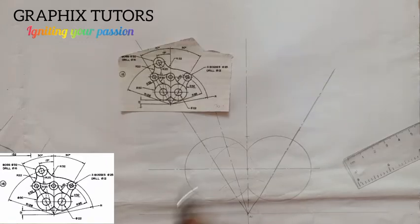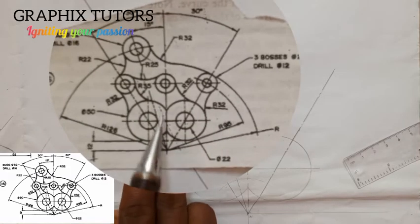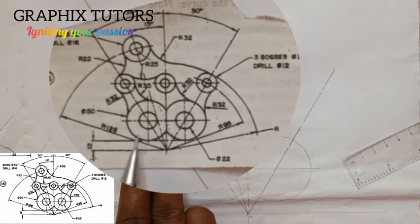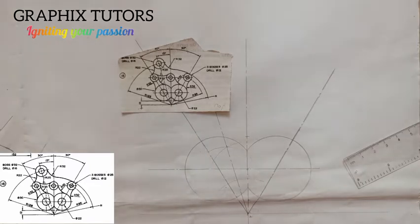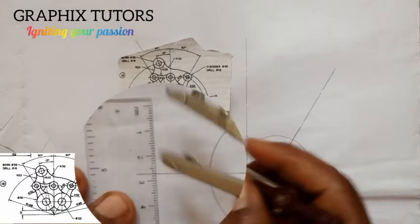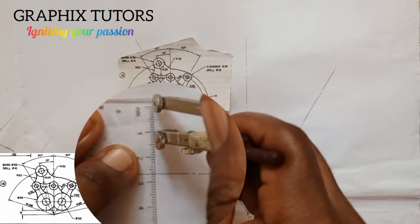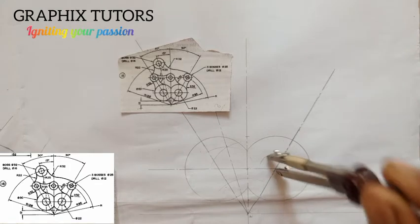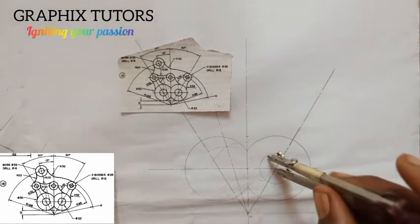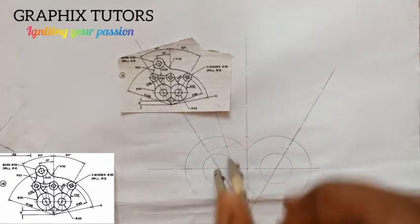So having done that, we've drawn these two circles, which have a radius of what? 25, both of them. And there's another one inside, and we're giving that one inside to be what? 22. Diameter 22, the radius is what? 11. So I'm going to measure 11 on my meter rule this way. This is 11 here. And I'll place it at the center. Then I'm going to draw a thick line. I'll come here also, and draw another thick circle here.